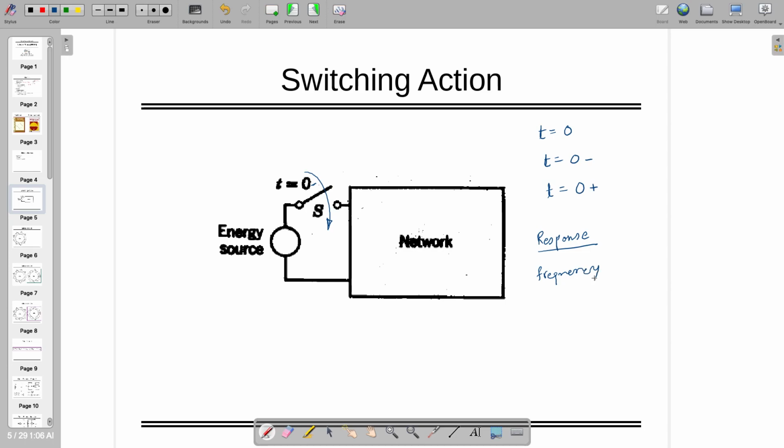If you are interested in frequency, any change in frequency, then you should go to Bode plot, right? But if you are interested in time response, we are not going to call it time, but we are going to call it transient response, right? Because it's with respect to time, it's toggling, it's ringing, so we call it transient response.